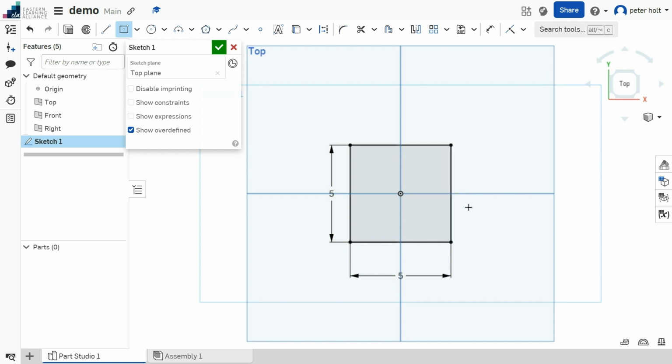If I've made a mistake and I've accidentally got rid of those two dialog boxes, up at the top, there is a dimension tool that looks like this. If I click on that and click on one side to another side, it will allow me to draw the dimension on. I'm going to press escape to drop that tool because I didn't want to finish it. And anytime I want to release a tool because I didn't want to draw, I can press escape.